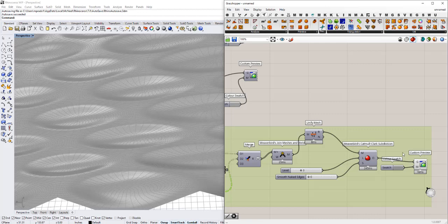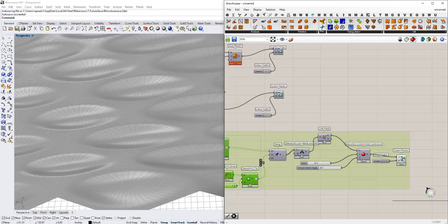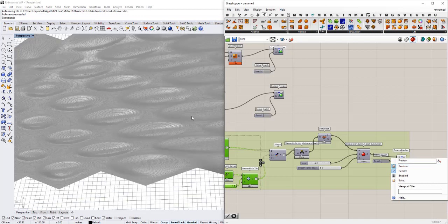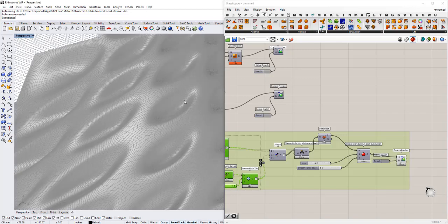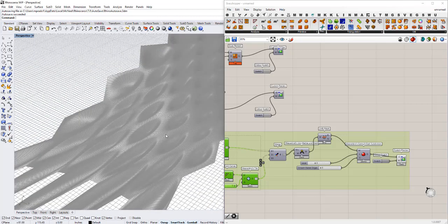Right? So one of your assignments is going to take whatever facade you made and generate a smoother version of that. See if you can work with the subdivision algorithms. And if things are not working, you might want to do things like joining the meshes, welding the meshes, unifying the meshes to get some connected curvature happening. Okay.